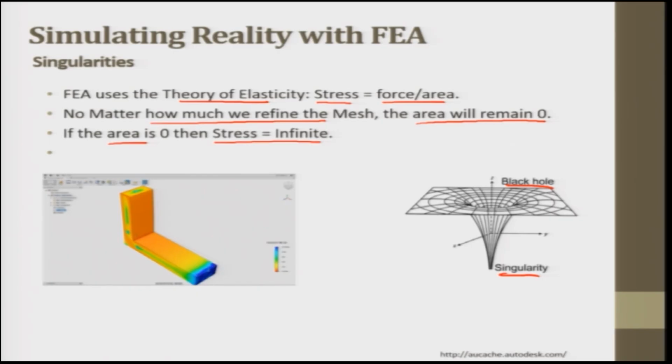So these are certain issues that a finite element analysis person faces. There are certain errors that could happen while we are conducting this FEA, finite element analysis. The modeling errors due to simplifications. We try to model for the real world, yet we are not able to do it 100%. More simplifications sometimes lead to error. Sometimes there are discretization errors that result from the creation of the mesh, where the discretization or the division of the mesh is not proper.